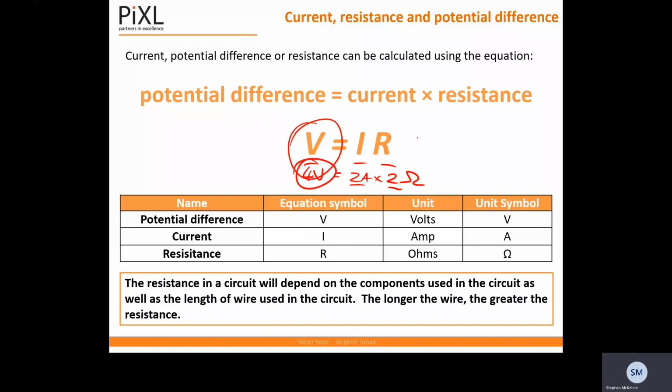The most common way you're going to see this is to calculate the resistance. R equals V over I. Again, sorry for this funny little line, I don't know where it's coming from. Voltmeters and ammeters are quite common, whereas ohmmeters are not as common. So in labs, in experiments, we tend to calculate the resistance using the voltage divided by the current.